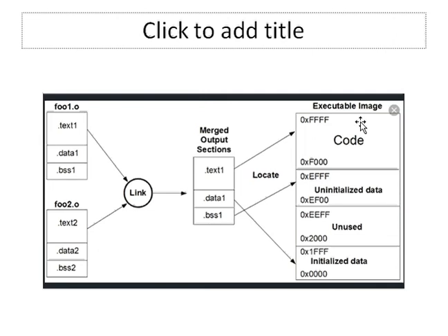Its linker looks something like this. Here this code region was addressed like this for your Cortex machine. This is not your code area, it starts from the beginning. The ultimate text file, including the code regions of these two objects, goes to this place. Then these two merged data regions go to the data segment, which is this region, the initialized data segment. So this is how your assembly code and translation works.